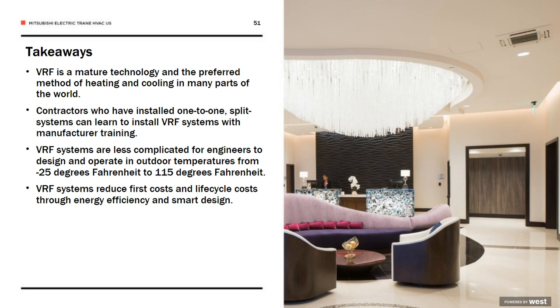Number two, contractors who have installed one-to-one split systems can learn to install VRF systems with manufacturer training, as Vic talked about earlier today. Number three, VRF systems are less complicated for engineers to design and provide for operation in outdoor temperatures from minus 25 degrees Fahrenheit all the way up to 115 degrees Fahrenheit, and in some cases a bit beyond. And VRF systems reduce first costs and lifecycle costs through energy efficiency and smart design.